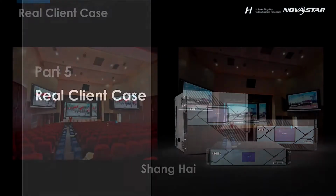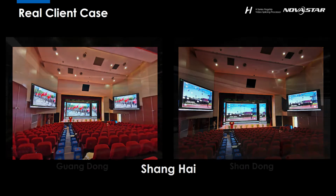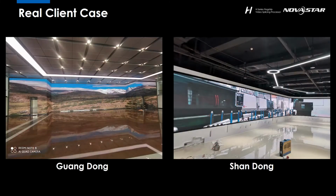For example, this is a 5-screen project in a grand hall in Shanghai. Traditionally, we have to use 5 sending cards and another splicer that has 5 DVI output ports for drawing the images as a whole. But now one piece of H5 can handle this. Input sources can be switched to where you want, with the multiple layers that you would like to open. Besides, the H Series is also good at handling such ultra-long screens, where the images are well synchronized, the resolution of the H9 is well set through EDID, and the large loading capacity can all show their brilliant talents.